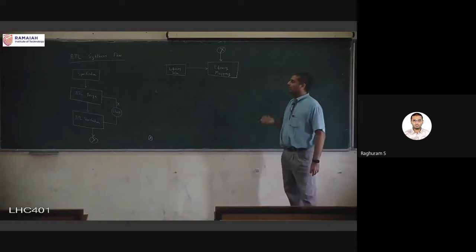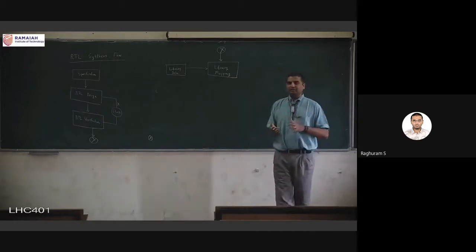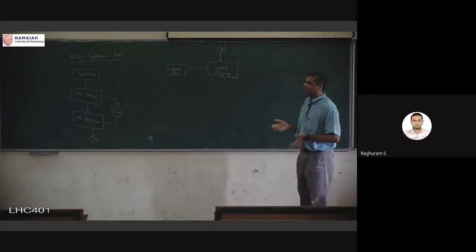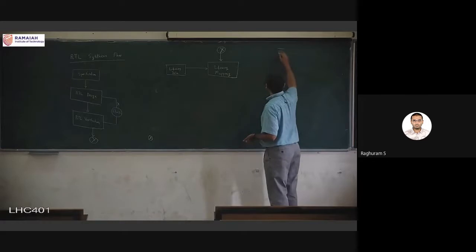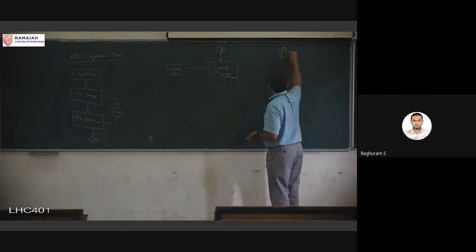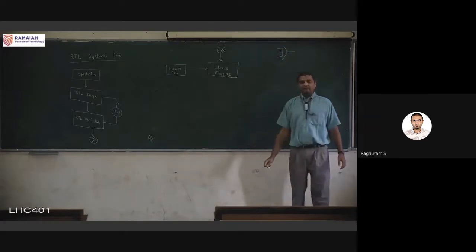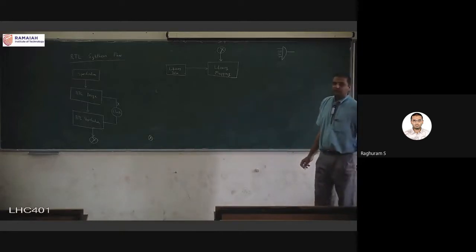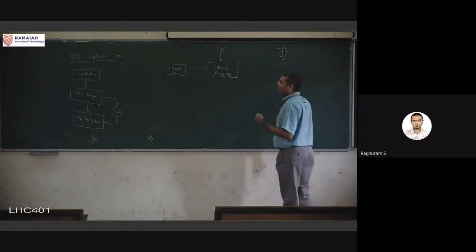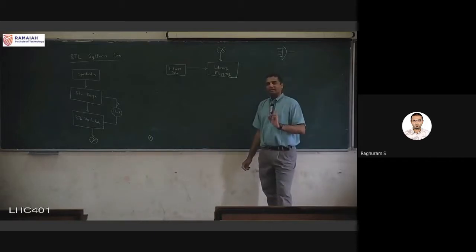This library is very important for us because we don't have access to all sorts of gates. For example, the gate level netlist might have produced something like a 5 input AND gate, but a 5 input AND gate might not be part of my library, and I want to produce a design that only consists of gates or cells, both are the same, from my library.